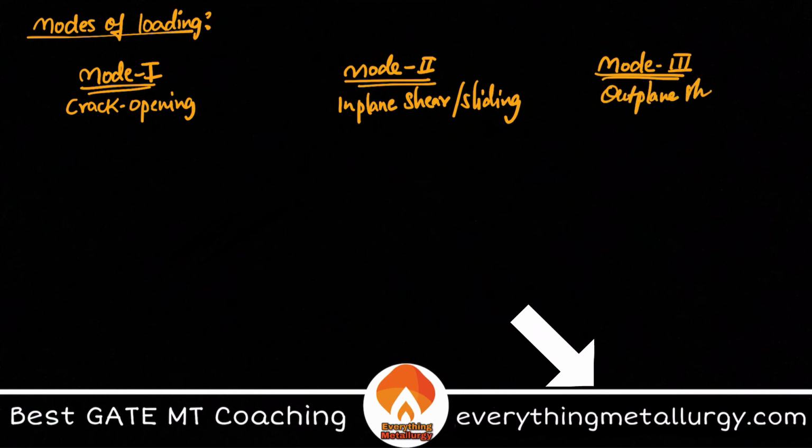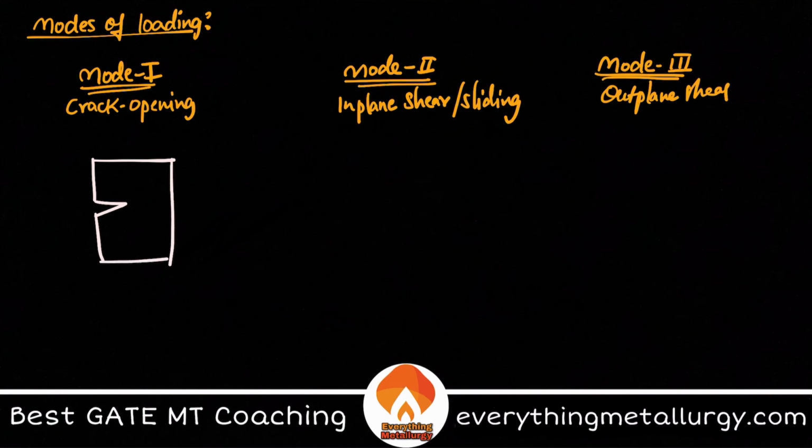So in mode 1, let me take a body which has a surface crack, and I am applying longitudinal stress. So what is happening? My applied load is perpendicular to the crack, so the crack will tend to open.